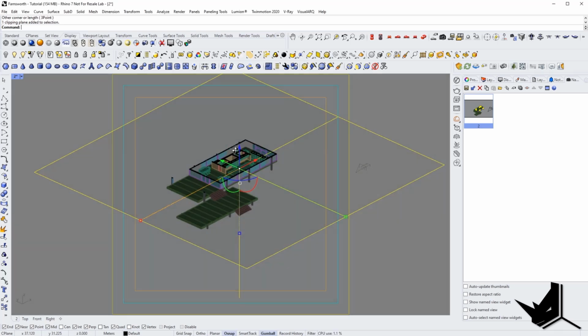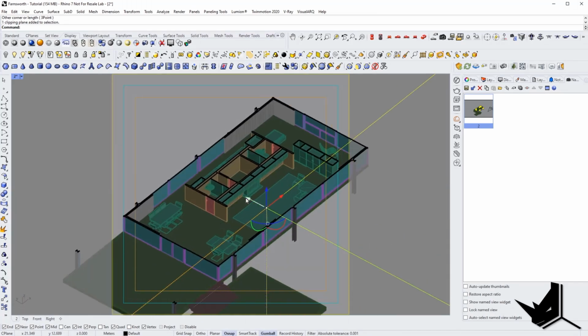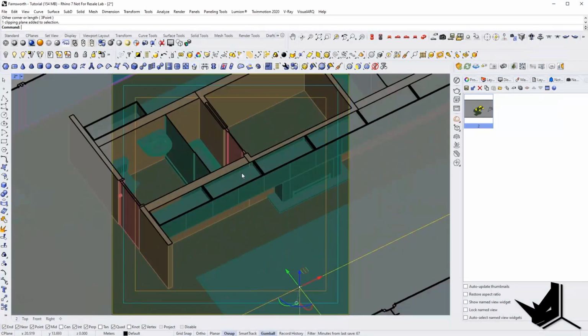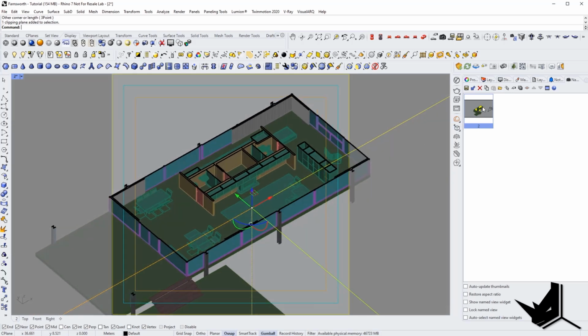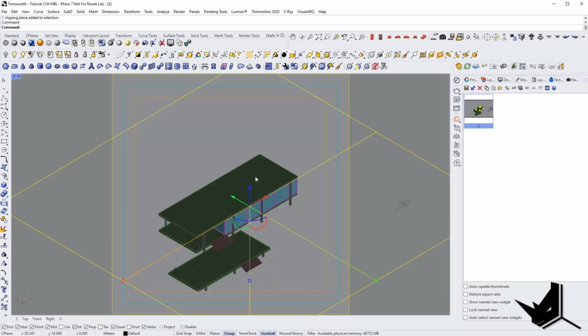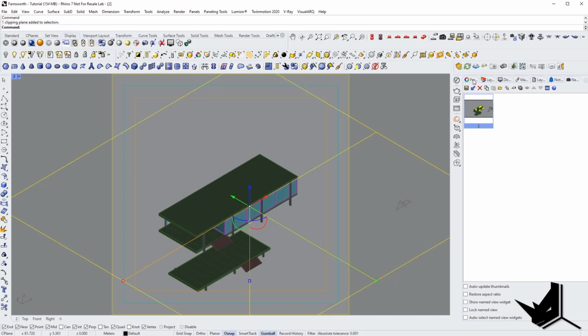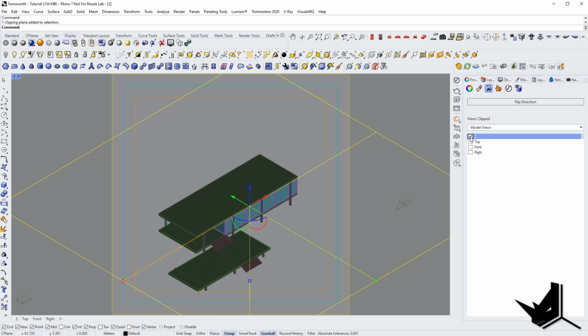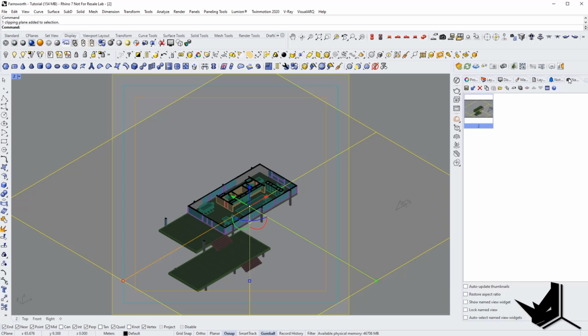And these were my settings for this base plan section. You can see here, if I zoom in, that those are the walls that are going to be intersected. If I come back here, you will see that if I want to activate this in my view, I need to click here, and then I need to click on number 2. This will activate it, and then of course if I want to save this named view, I need to resave it again so that it memorizes the change I just did.